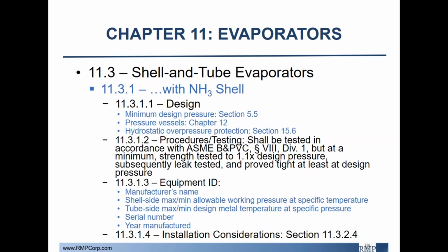So if the ASME code is more conservative than the 1.1 times the design pressure requirement, then you need to use the ASME code. So there's a little bit of nuance there as far as what should be used.